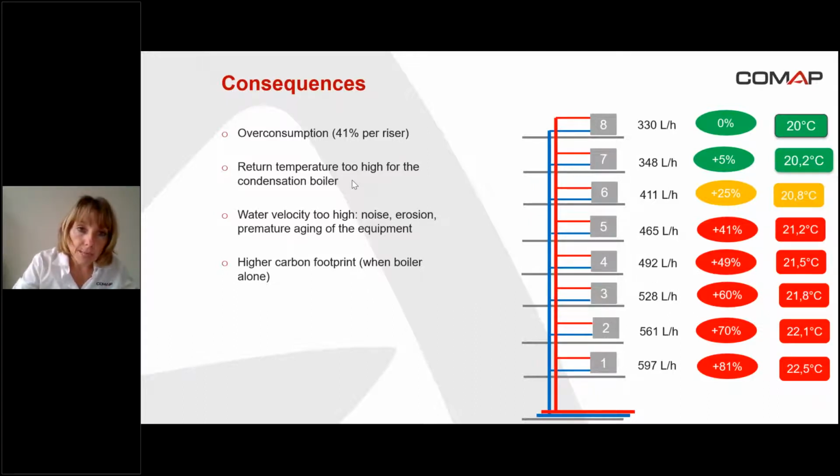At the same time, if the flow is higher than expected, that means the water velocity is also too high. And if the water velocity is too high, that leads to noise, to erosion, and if there is erosion, that means a premature aging of the equipment. So it costs also regarding the equipment.